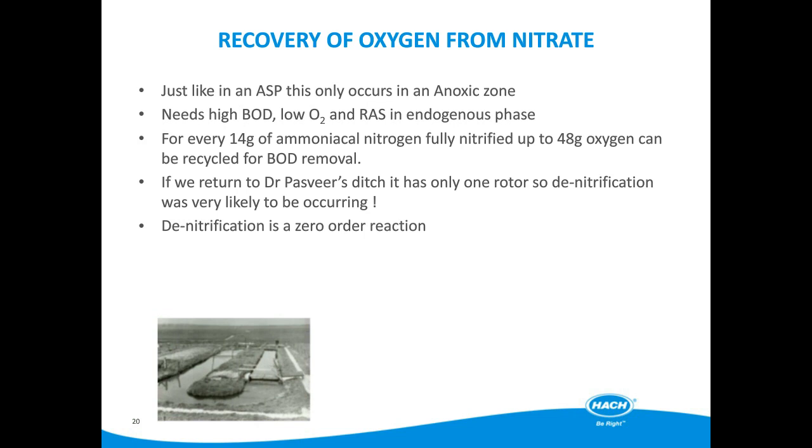One thing to note is that denitrification is a zero-order reaction. This means that the rate of denitrification is independent of the concentration of nitrate, but is dependent upon the availability of BOD and the DO concentration. The zero-order reaction kinetics hold true until the concentration of nitrate drops to very low levels.